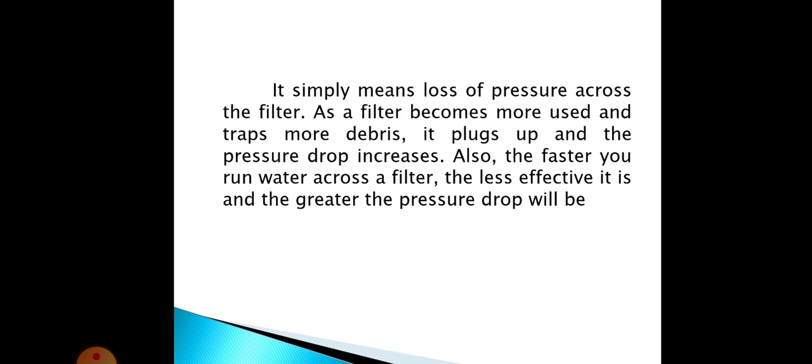Now also we can say that head loss just means the loss of pressure across the filter, and as we use this filter unit for a long time, the debris or the particles that are present in water will be arrested by the sand particles or the filter media. So these debris will plug up, and then the pressure drop will increase. And also the faster you run water across a filter, the less effective it will be and the greater the drop of pressure will be.